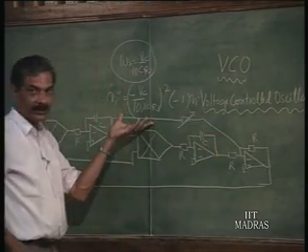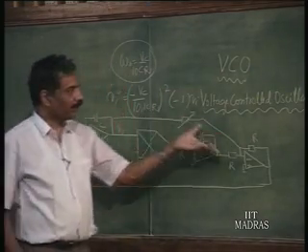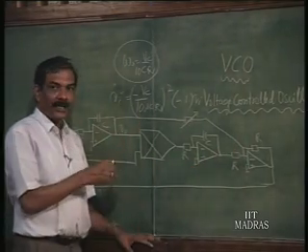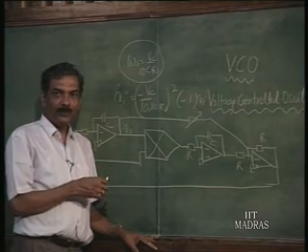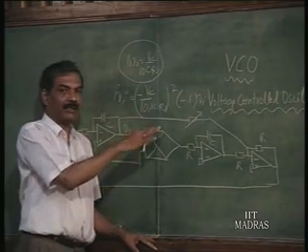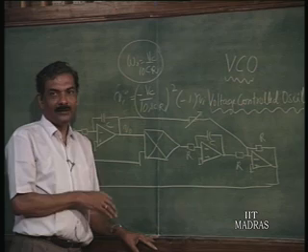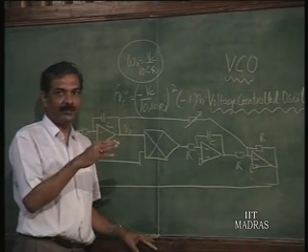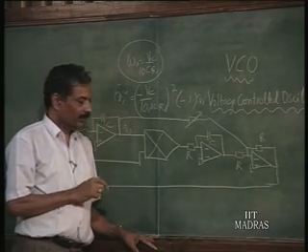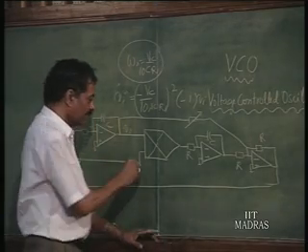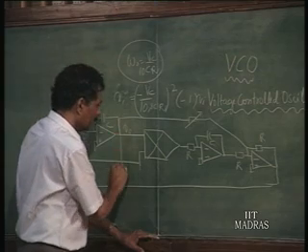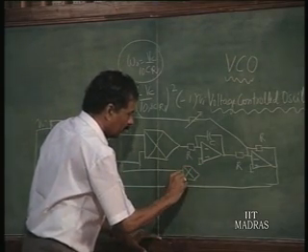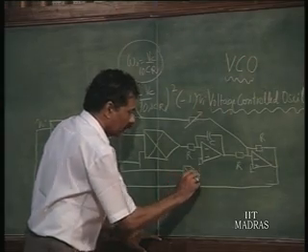So, you might have to give a positive feedback in order to make this go into oscillation, right. And you can bring about again the amplitude stabilization loop, such that the positive feedback is there only when the amplitude is 0, and the positive feedback gets compensated by the negative feedback exactly at the required amplitude. All that can be done by using again a multiplier from here, can put a multiplier here, okay, and then